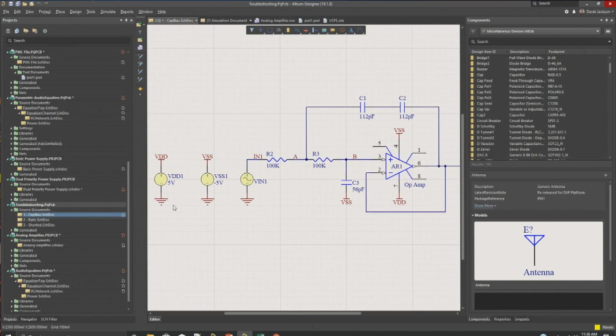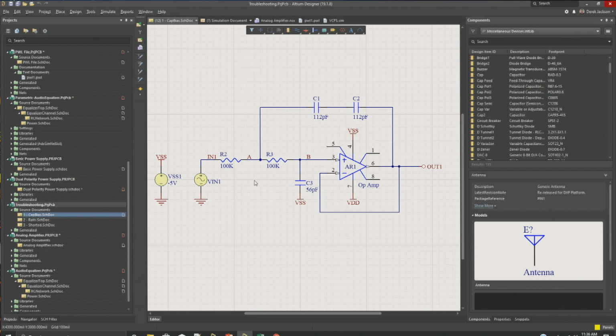Like this one is for capacitor bias. Although you really don't see a scenario like this where you have two capacitors in series, if your circuit happened to run into something like that, because capacitors are opened up with the initial bias, it opens up all capacitors, shorts all inductors, and calculates that initial operating point. If it can't find a point, it'll fail.